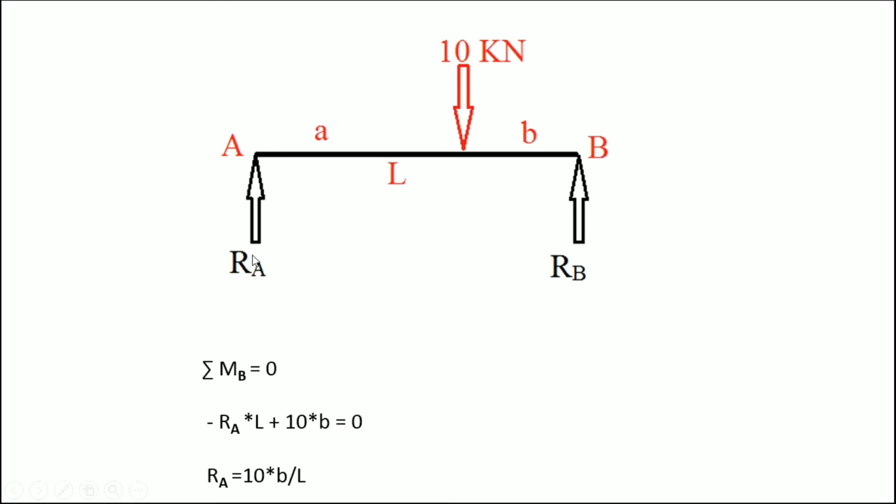RA into this complete distance L. RA into L. And as this is creating a clockwise moment here, RA is forcing the member in the upward direction. That's why, if we are considering moment at point B, that means with respect to point B, reaction RA is creating a clockwise moment.